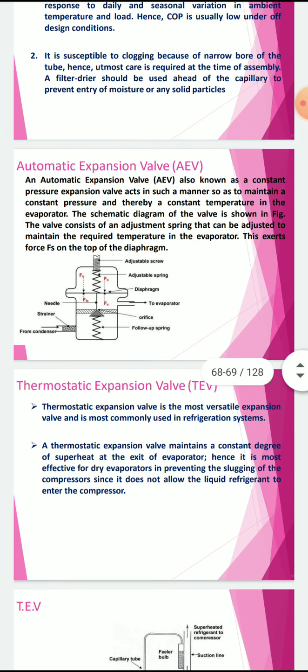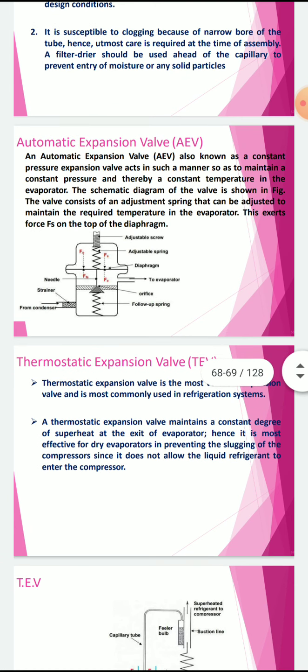The valve consists of an adjustment spring that can be adjusted to maintain the required temperature in the evaporator. This exerts force Fs on the top of the diaphragm.